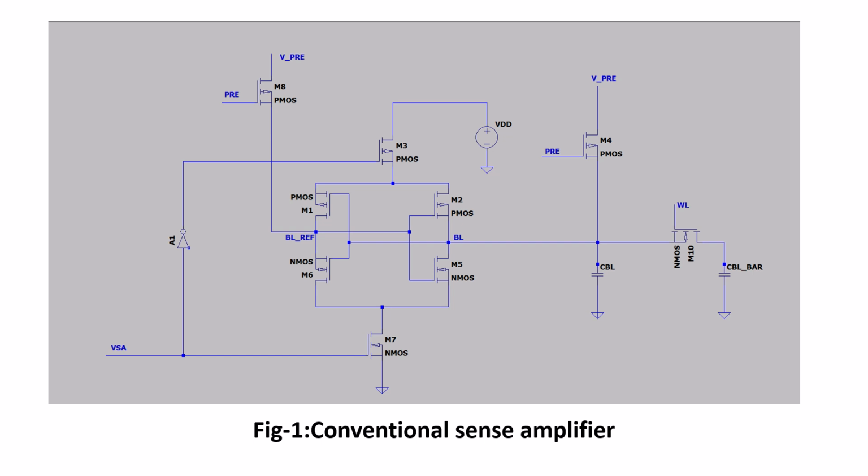So this is VDD by 2 plus delta V. So definitely this NMOS is going to be turned on. I mean the overdrive of this NMOS is greater than the overdrive of this NMOS because this is at VDD by 2 and this is VDD by 2 plus delta V. So essentially the overdrive of this NMOS is greater than this NMOS.